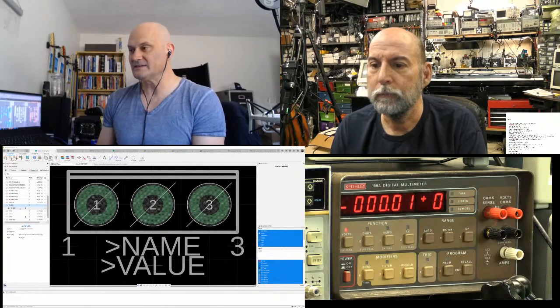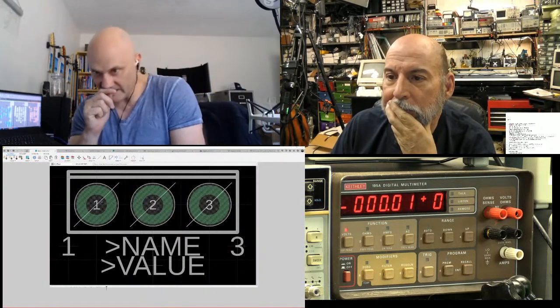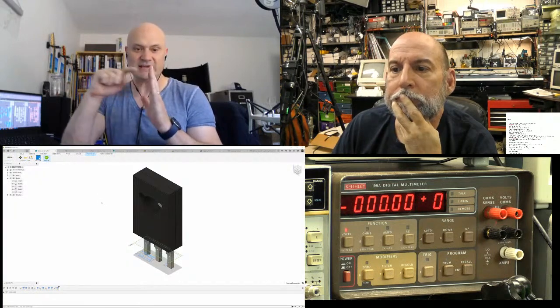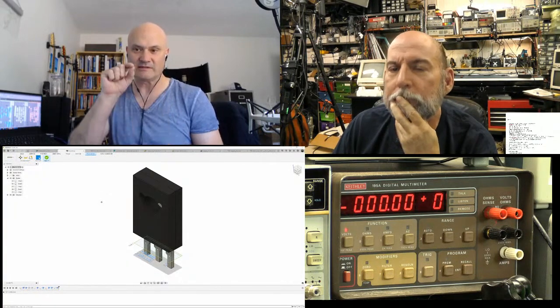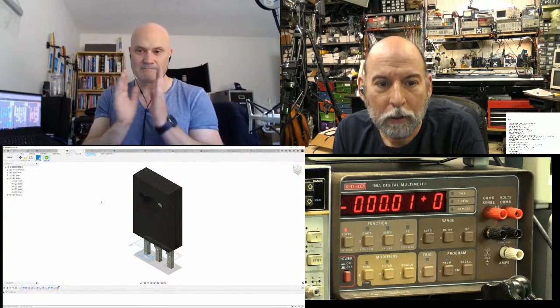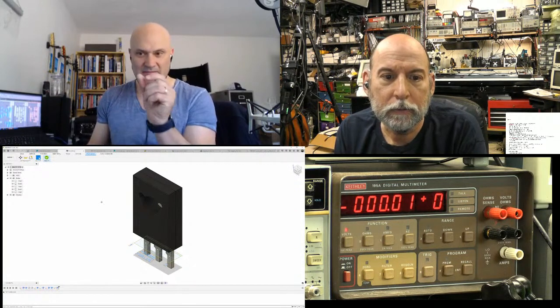Now the package, I believe this is the one. You take a data sheet and you get the line drawing of the package, and it's got that JEDEC standard table of dimensions with labels, right. A, B, C, D, little b for the pin spacing or whatever, and little e for the pin width.